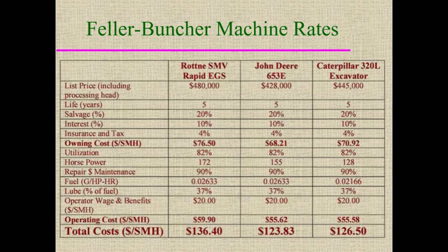We also consume fuel at a particular price, and the lube is oftentimes a percentage of fuel costs. On machines that do a lot of movement, it's not uncommon to have the lube be 50% of the fuel price. Now, as this fuel price skyrockets, that percentage should probably drop back because lube and other expendables haven't gone up at the same rate as fuel.